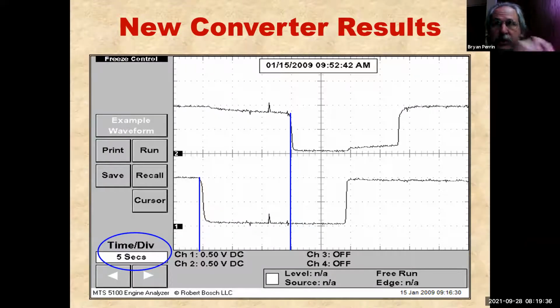So now I'm down to just testing the catalytic converter. The other thing that's really cool about this test is I can do a before and after, as you saw here. I can see how much did I have before, how much do I have after. If I'm doing 2 banks, a bank 1 and a bank 2, now I can see, hey, here's my bad bank. Now I put the new catalytic converter on.